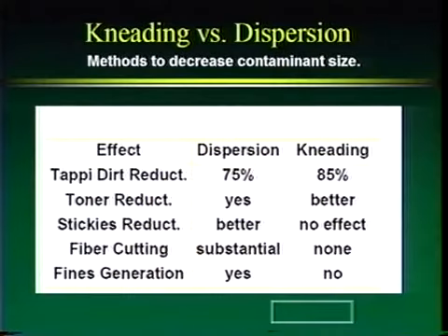Fines generation just kind of follows that fiber cutting. So we're going to generate some fines in disc dispersion, but in kneading we're not going to generate as many fines because of the gentler action of the fiber-fiber rubbing rather than the metal to contaminant or metal to fiber action.